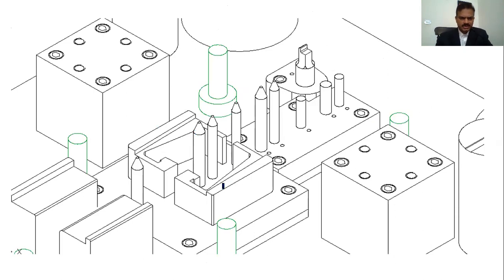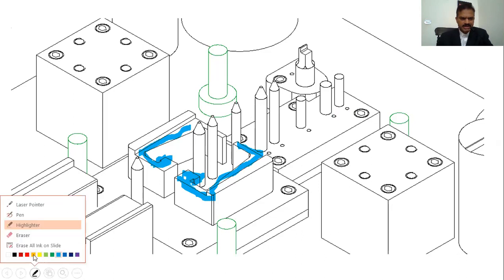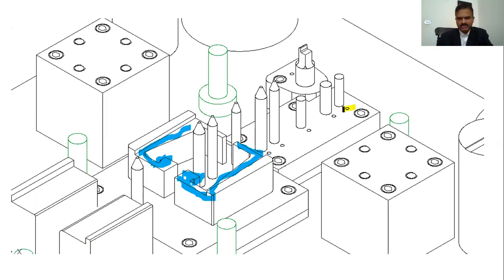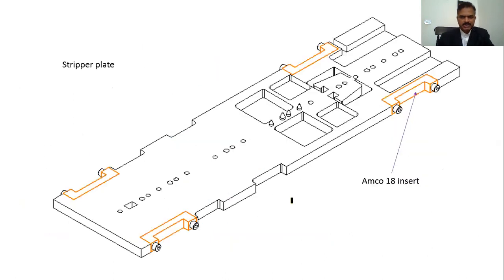Closer look. These are the cutting punches. The profile. And this is where you need to maintain some extra material for shaving it on a later operation. Just have a look at these holes here. We'll come back and discuss what this is about. See some holes here. It's on all the punches and pilot. I'll come back and explain to you what that is.